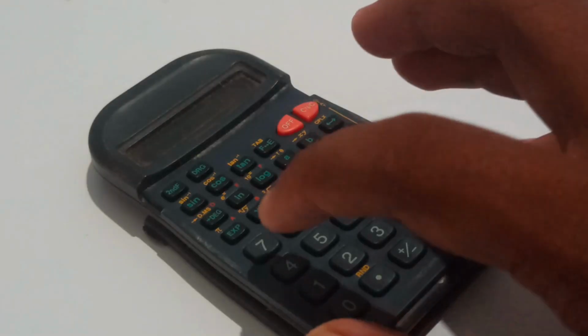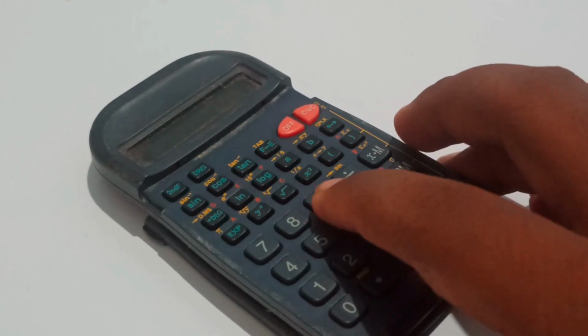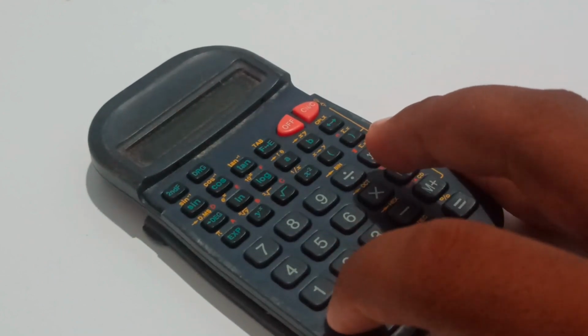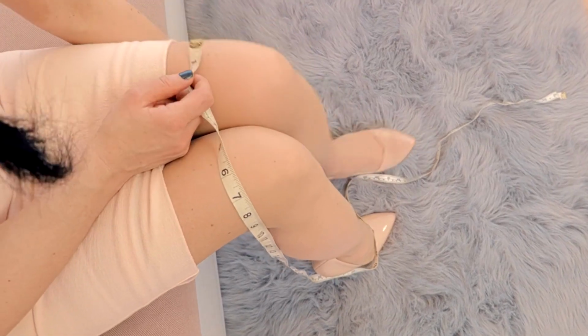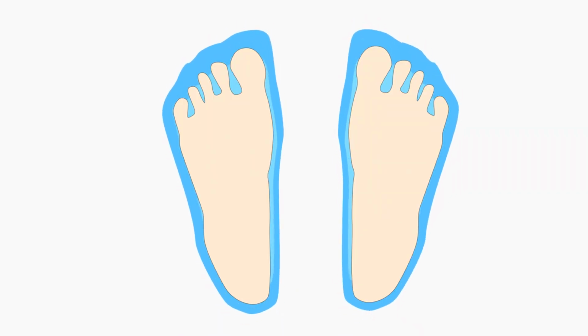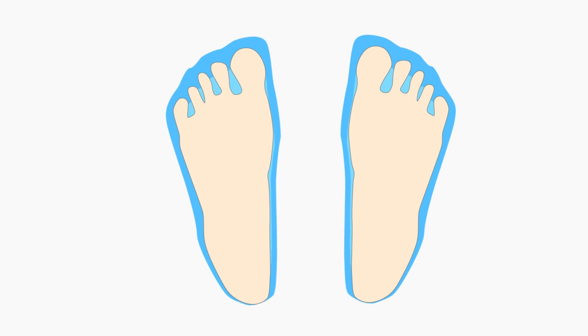140 minutes. Remember that there are 60 minutes in a degree. So, to work out how many degrees you divide 140 minutes by 60, so 140 divided by 60 equals 2.33 degrees. You can convert 0.33 of a degree into minutes, taking the decimal portion of the number, i.e. just the digits to the right of the decimal point, and multiply it by 60 minutes in an hour. So, 0.33 times 60 equals 20 minutes. So there is 2 degrees 20 minutes of extra variation to add to the variation figure of 1979, which was 18 degrees 48 minutes E, or 18 degrees 48 minutes plus 2 degrees 20 minutes equals 21 degrees 8 minutes E.